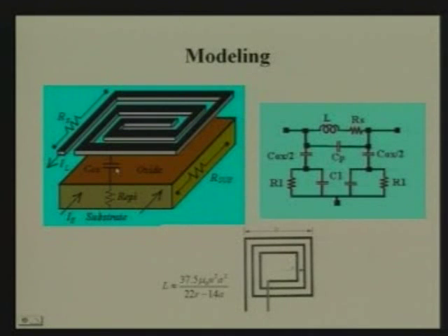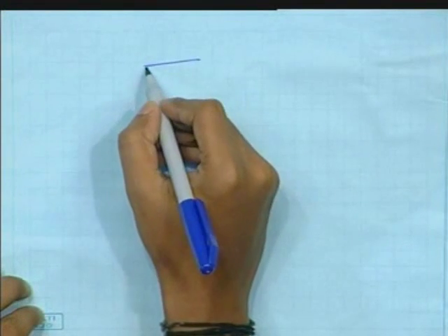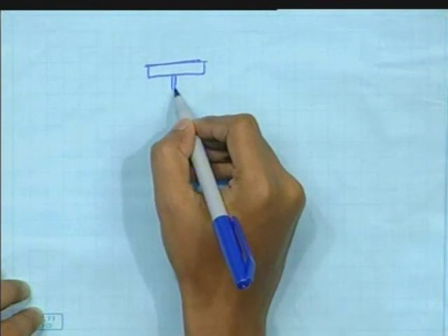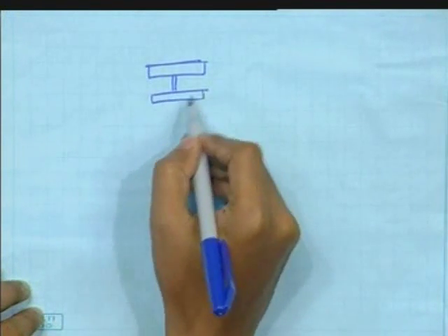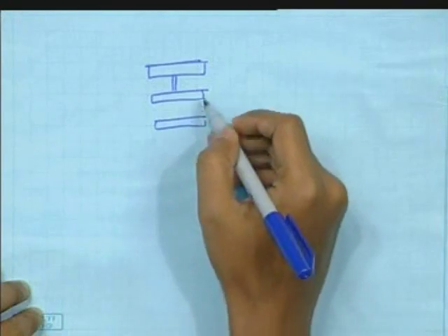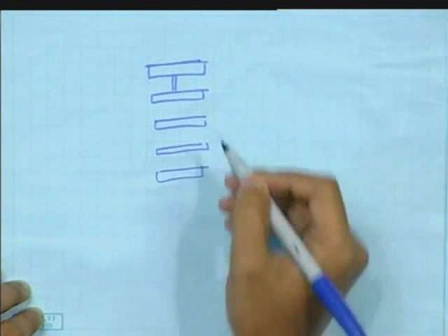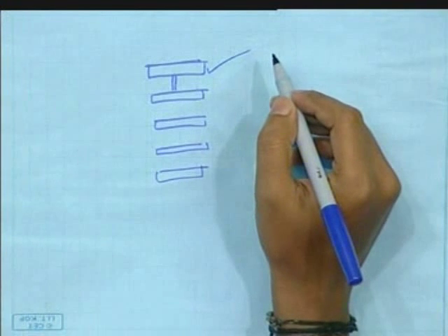Okay, see the CMOS metal layer structure is, this is the topmost metal layer. You can either connect by vias to the bottom layer structures. Say there are say 6 metal layers in a 0.18 micron CMOS process. So we are using the top metal layer to fabricate this type of structure.